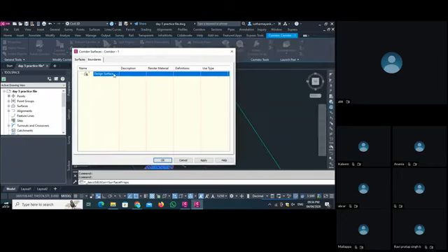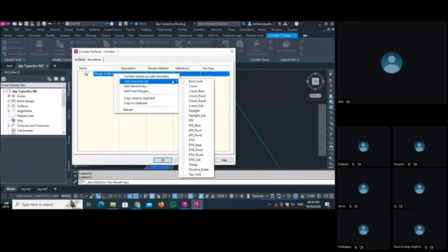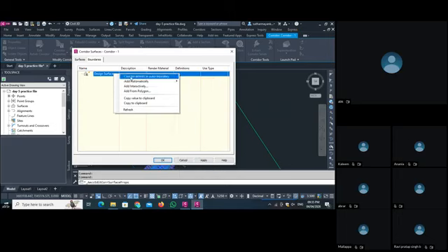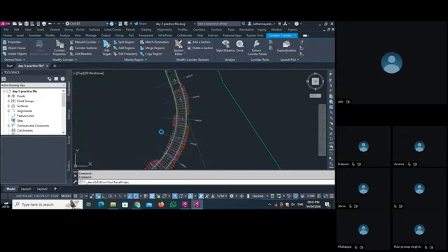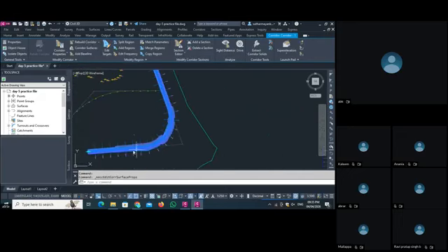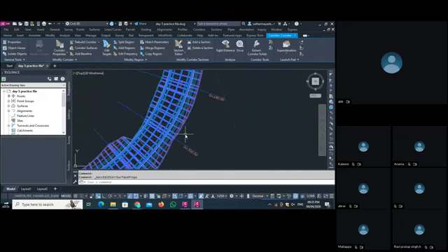So I right click here and set corridor extent as outer boundary. There is another option to set the boundary as per our requirement, but I set the outer boundary. I select here and now the boundary is set. Then I click apply and OK. Now your corridor surface is created.